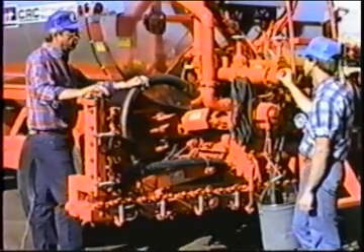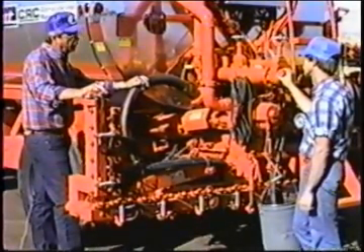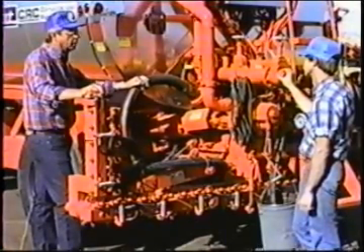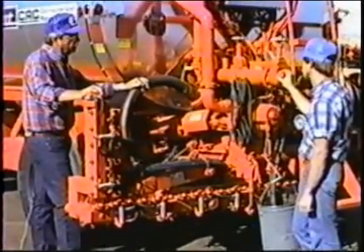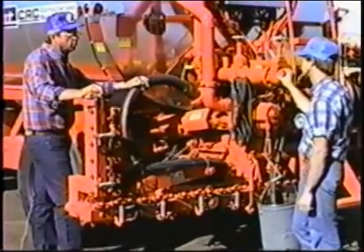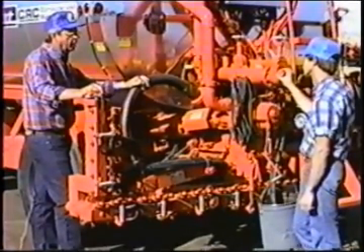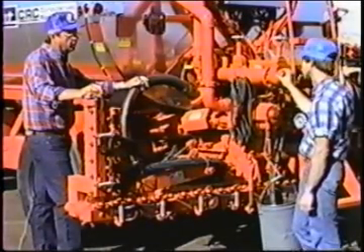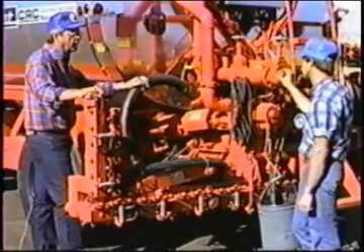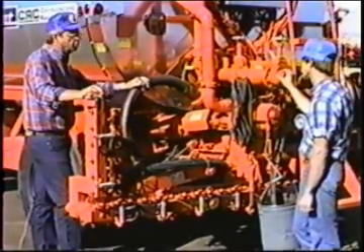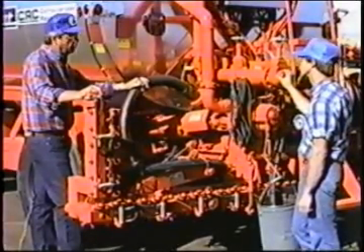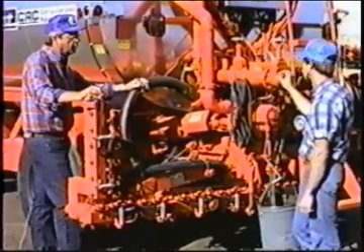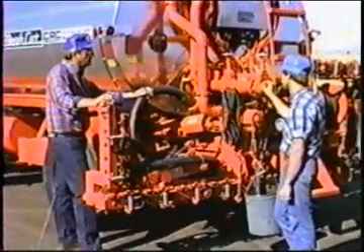That is 10 revolutions in 1 minute. 10 times 0.48 is 4.8 gallons. If we were to turn it 100 revolutions a minute, it would move 48 gallons a minute. If we turn it 1,000 revolutions a minute, it's going to move 480 gallons a minute, and anything in between. The speed of the pump multiplied by that number 0.48 gives us the gallons per minute that it is pumping.